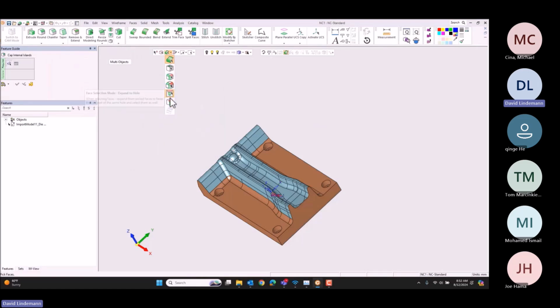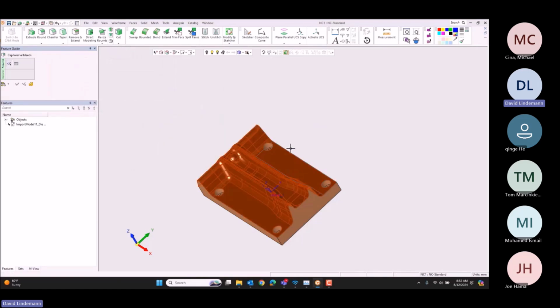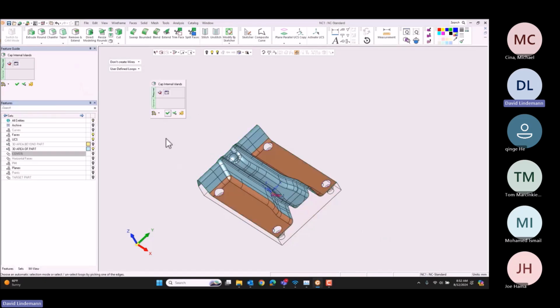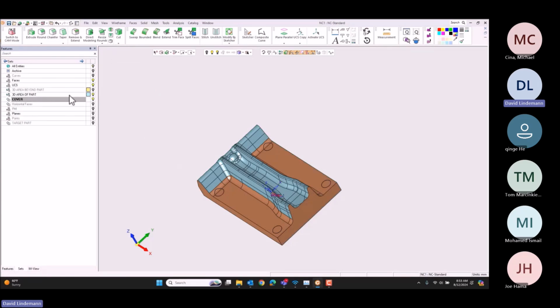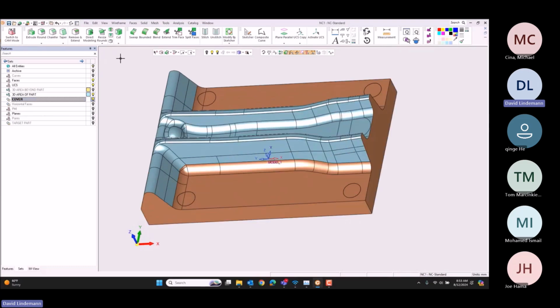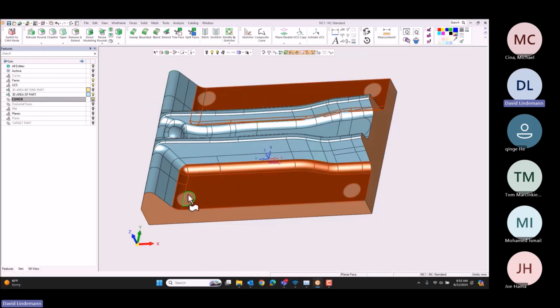I've got a couple of drill holes for socket head cap screws. I want to fill those up, so I've got quick functionality just to find the tops of those holes, fill them into place for me so that I know I'm not going to let the cutter accidentally waterfall down into there. All right. And understanding that what I'm really doing here is teaching the software the way I like to cut as I go through this process of setting this up in a few minutes.